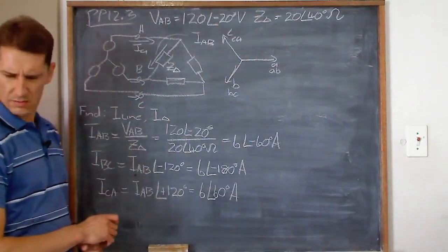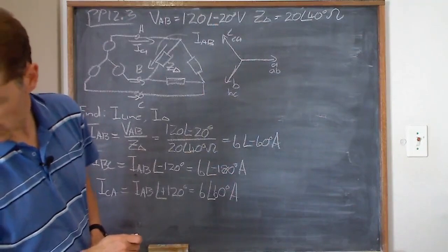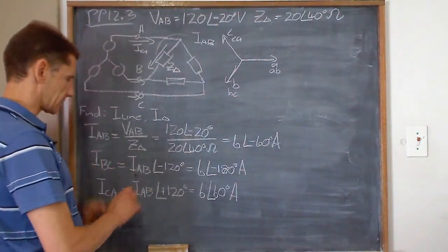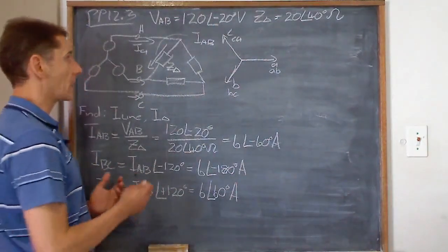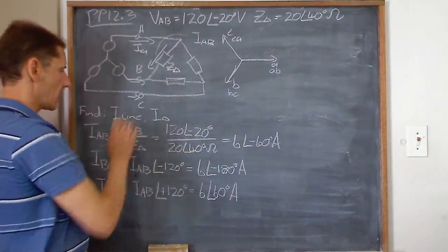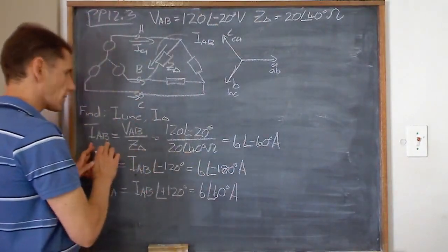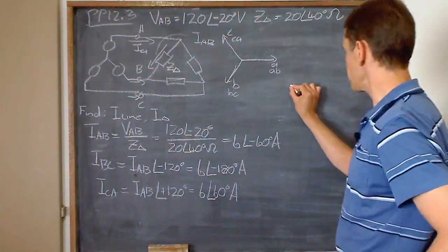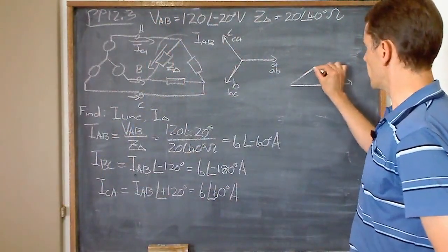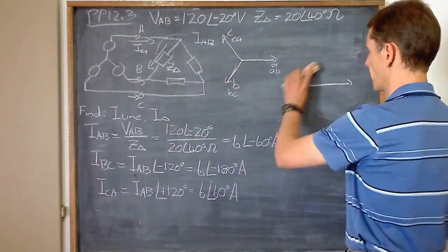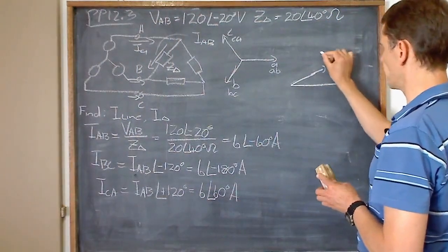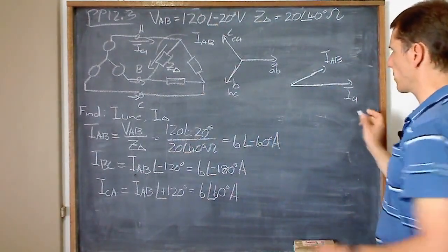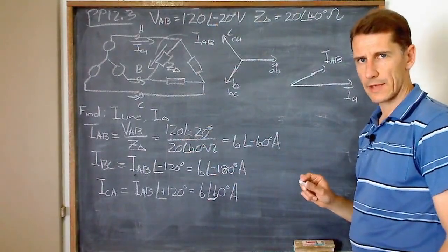What the textbook talks about, let me just check. Remember that the textbook says phase currents, confusing delta currents. Okay, now I want to get my line currents, IA, IB, IC. Once you've got IAB, that second diagram that we've learned, the long one, that's not 30 degrees, but you get the idea. The short one, IAB, IA. That is how I convert between the line current and the delta current.